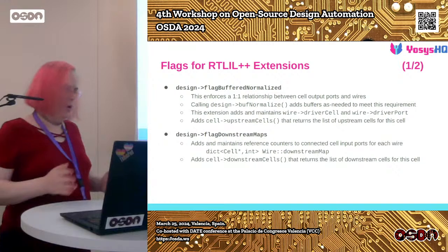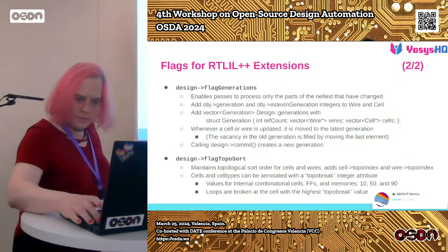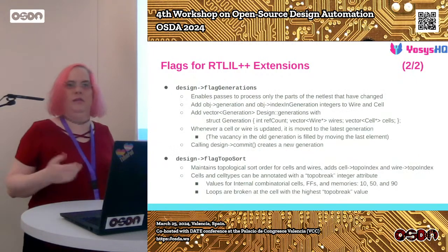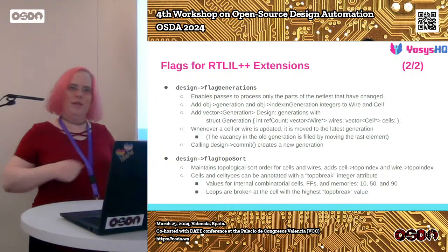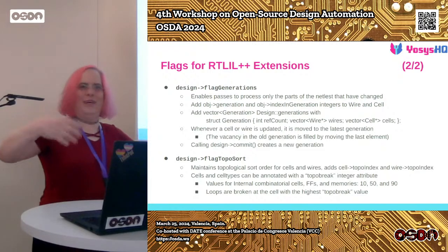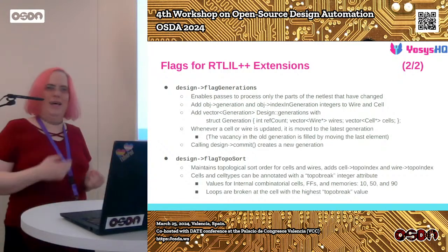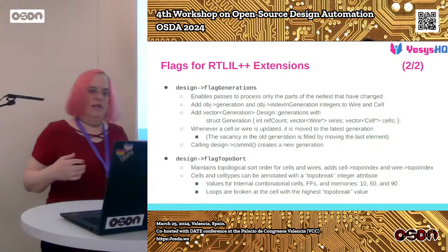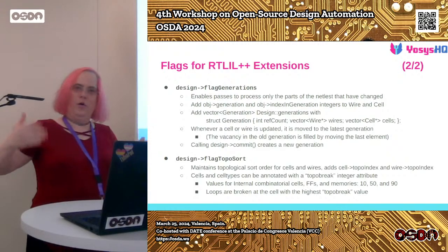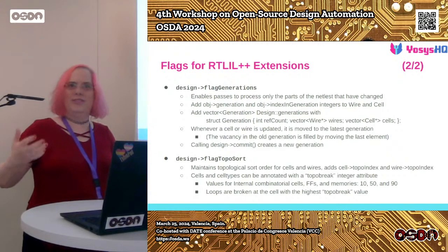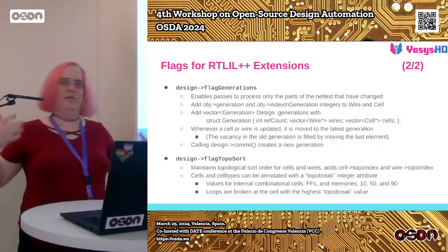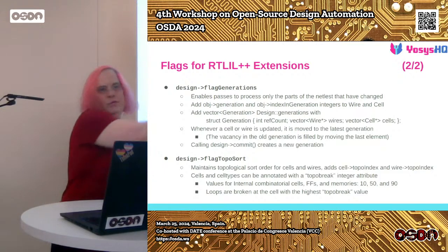And then we can narrow down where things happen. Multiple inputs, and add one more integer again by design. So whenever we update something, we increment the global generation number, and we set the generation index for that one thing. We essentially have a way of telling the index at generation, where we do not actually update things that are unchanged, and then run certain optimizations whenever the optimization opportunity arises in the netlist naturally, via an update function that will then apply the trivial optimizations we would want to be able to apply at every step throughout the flow.